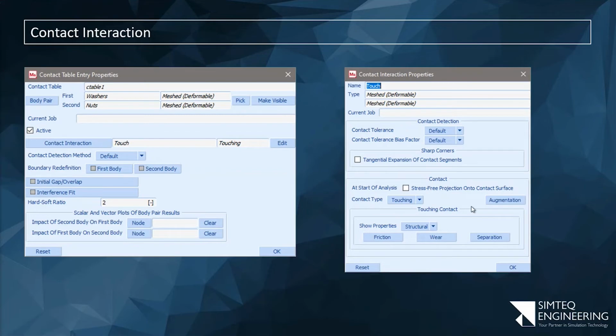Additional things we can define there: if I don't want to do weird calculations or weird separation requirements, in other words, I may say it should allow a certain tensile stress, but only then separate. So it's not something we use often. Same goes for wear. You can calculate it, but you need to know the wear properties. The most important one is probably friction.